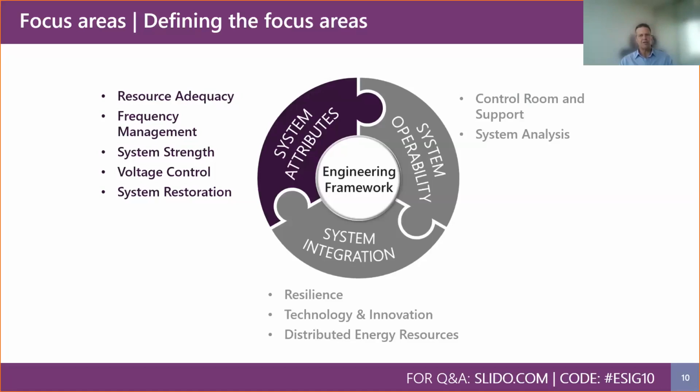But essentially, the focus is on NEM critical issues of incentivizing primary frequency control, which was only mandated through a rule change last year on a 3-year trial basis. We also need to establish minimum inertia levels to operate the system. We're also looking to define the fast frequency response services arrangements and the effectiveness and need for emergency frequency control systems.